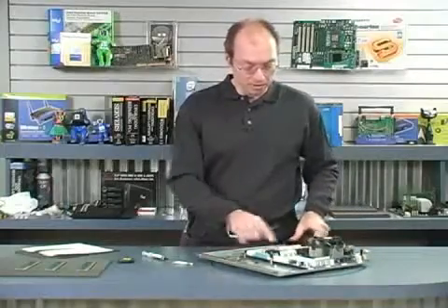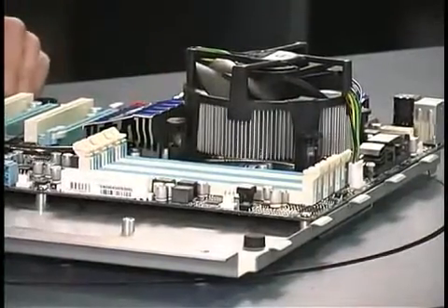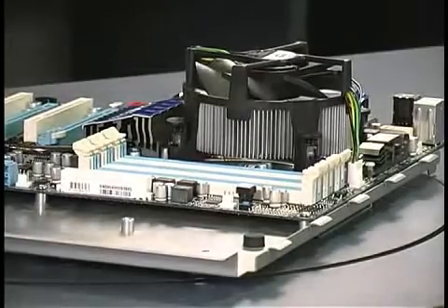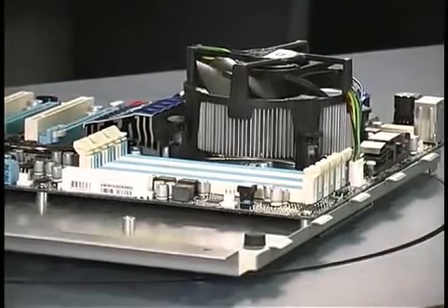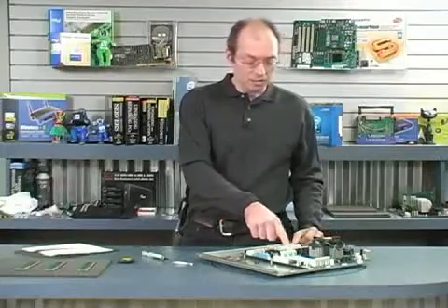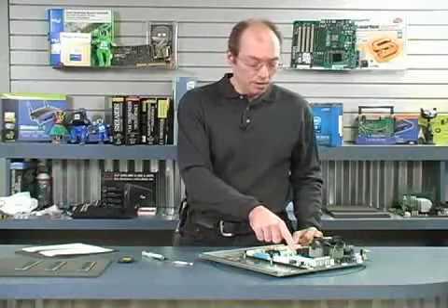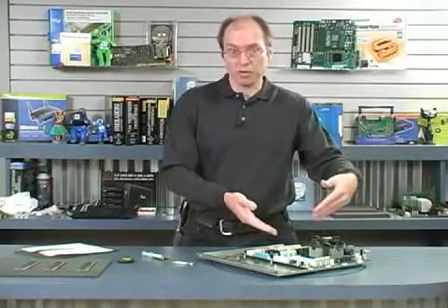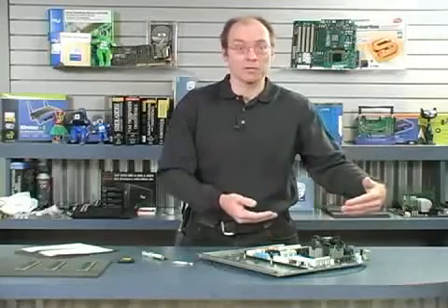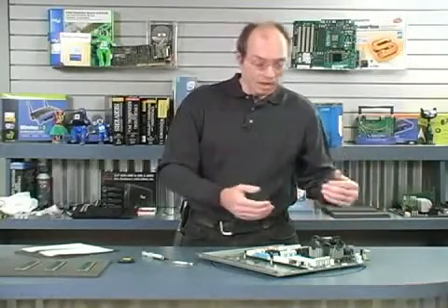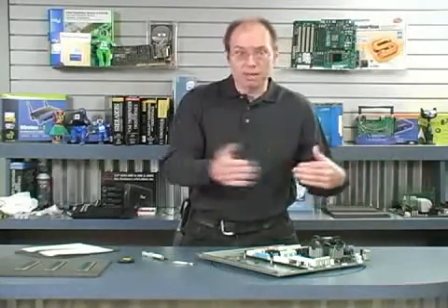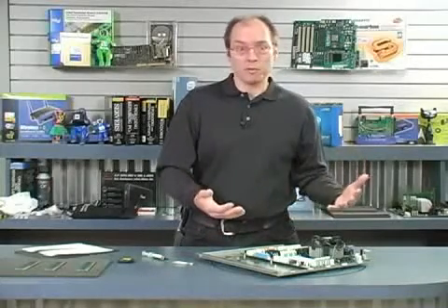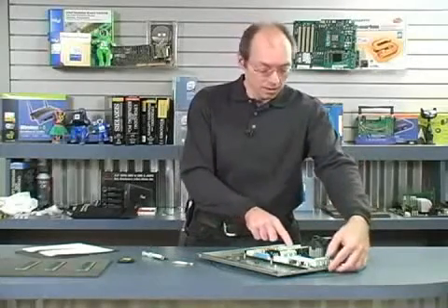Now, the memory is going to be installed in these sockets here. This uses a triple channel memory, so we are installing memory modules in groups of 3. And you can see 2 different sets of 3 sockets here. There are 3 white sockets and 3 blue ones. According to the manual for this motherboard, we need to use the white sockets first. That's the first channel, the first set or bank, and then the blue sockets are the second. So since we only have 3 modules, we're going to install them in the white sockets.